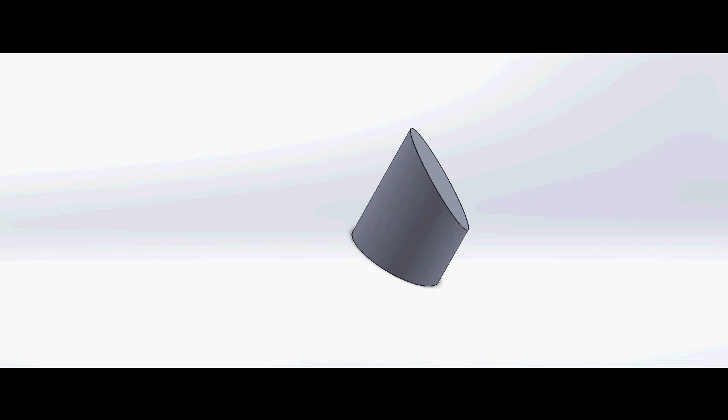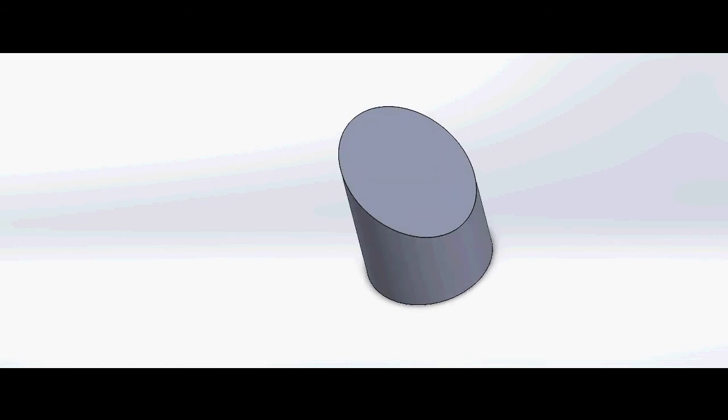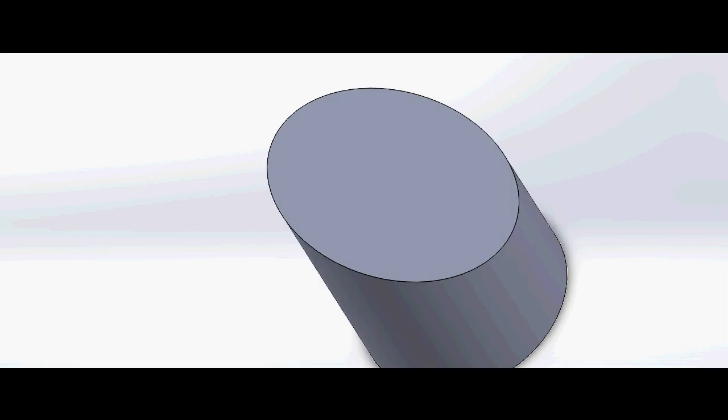Now we move on to the case where an ellipse is observed as a circle. We can clearly see that the top face of this cut cylinder is an ellipse. But when this cylinder is observed from a plane of projection that is generally referred to as the top plane, we observe a circle instead of an ellipse.